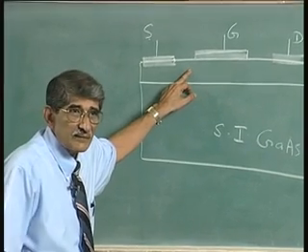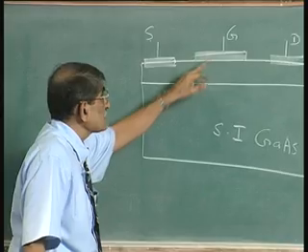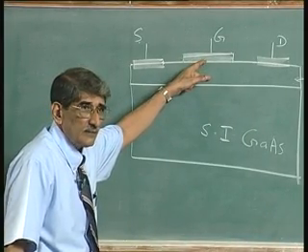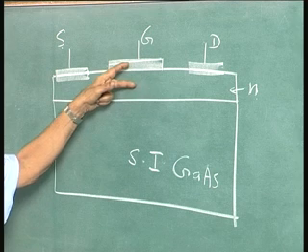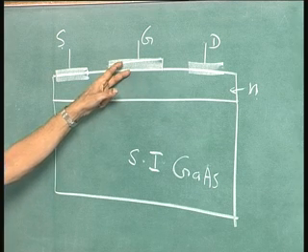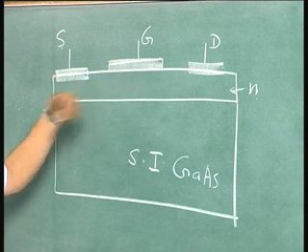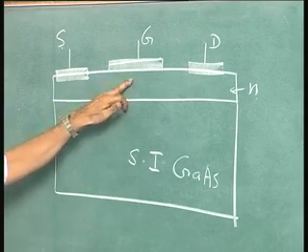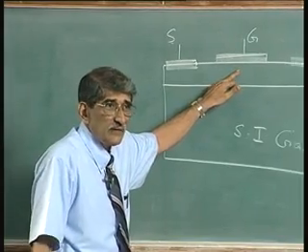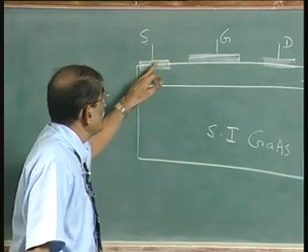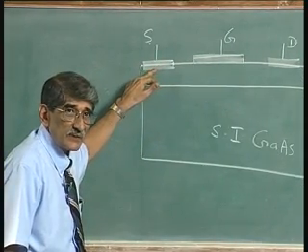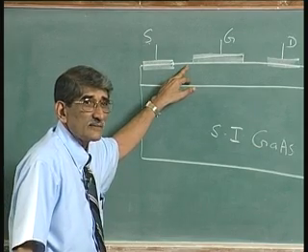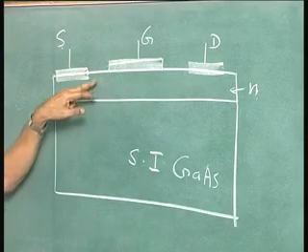In the example that we have considered, we had first discussed Schottky barrier, metal semiconductor contact. We saw the impact of the interface state density on the barrier height. We will see how the barrier height affects the current or the blocking capability soon. Qualitatively we have discussed, we will have quantitative discussion now. This we have discussed, make it N plus to make ohmic contact. Here, this free surface, what will be the effect of that? This is N type free surface.